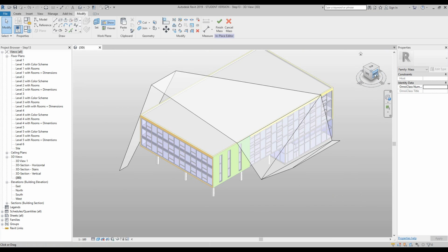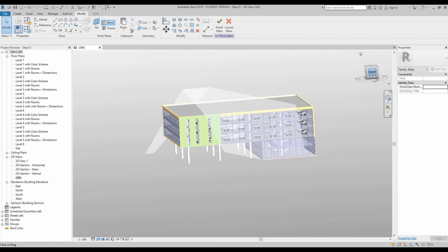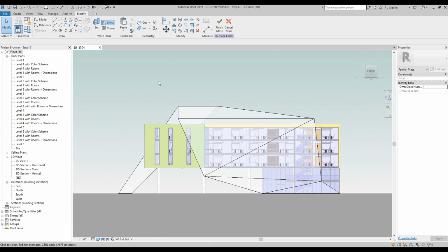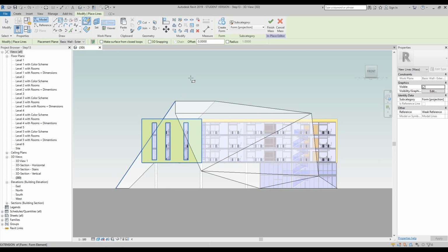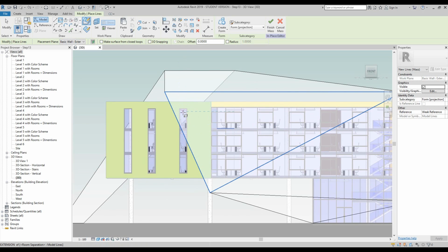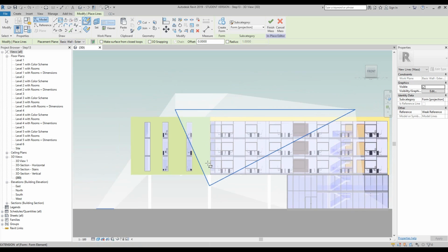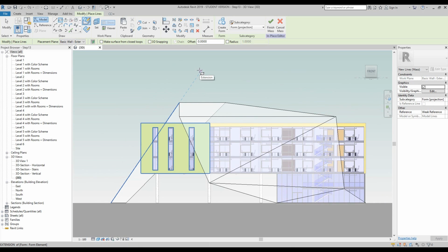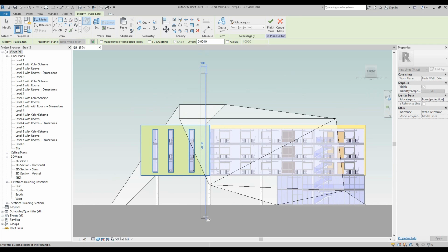I would like you to set the view to front on your view cube. Now again with the line tools we're going to create some voids first, so we're going to create some shapes and then cut it from the mesh. So if we choose our rectangle tool, we're going to draw a vertical rectangle pretty much between the far right long vertical window and the curtain wall. So pretty much from here all the way down to about here,